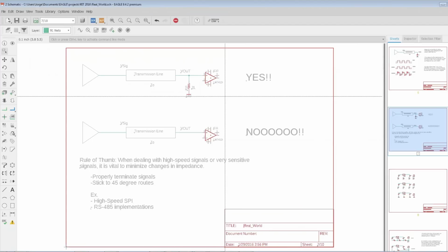You have a signal path and a return path, and that happens for every single net. If you think in those terms, you can become more aware of how your signal is behaving on the board, and that can help you troubleshoot issues. Those are the key concepts we want to talk about here.